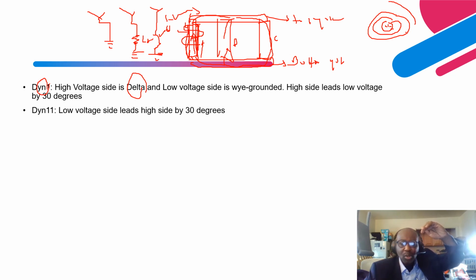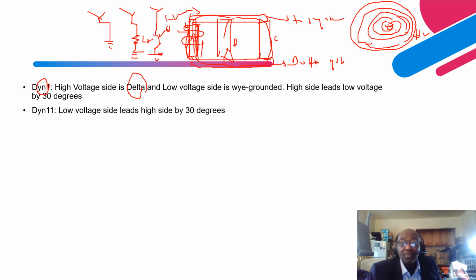Then you have the high voltage winding, like this, right? In between, it's what they call the air gap, where basically oil is flowing to remove the heat, right? So basically all the cylinders act as an insulating barrier between the high voltage and the low voltage, right?